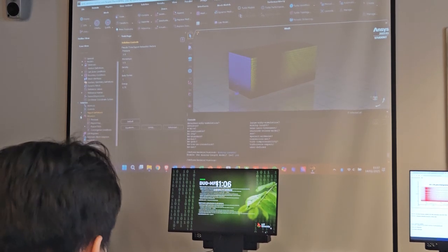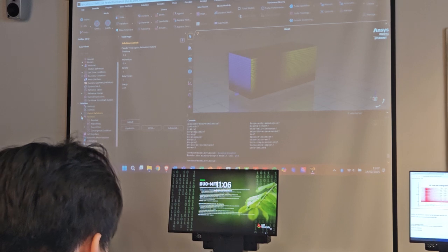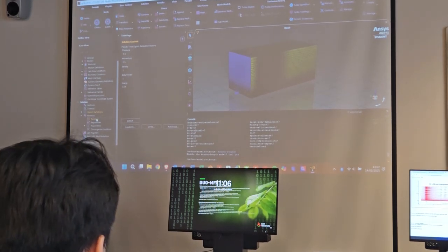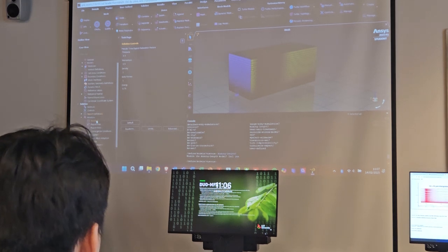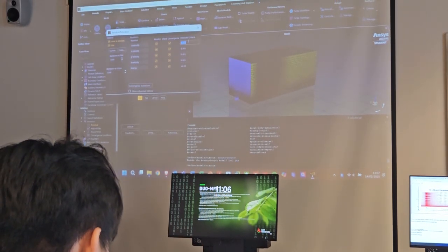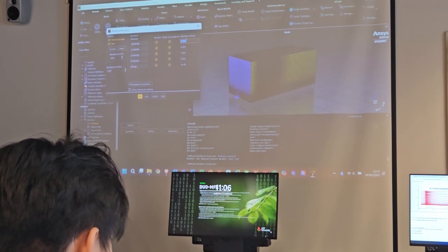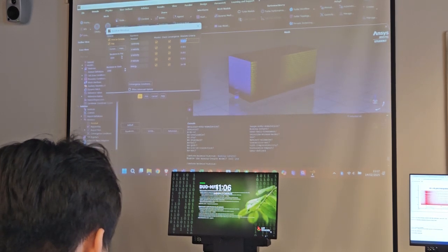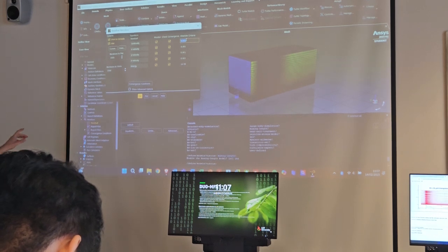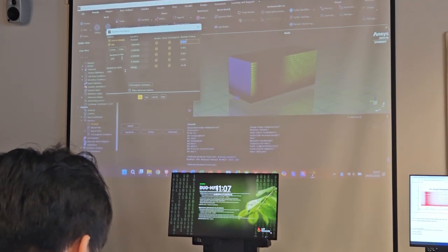Then the next thing is in monitor. If we expand that, you see that there is residual. So if you double click on residual, you can set the criteria for which you say, okay, now I got convergence. So residuals of the equations are typically a good way to monitor convergence.